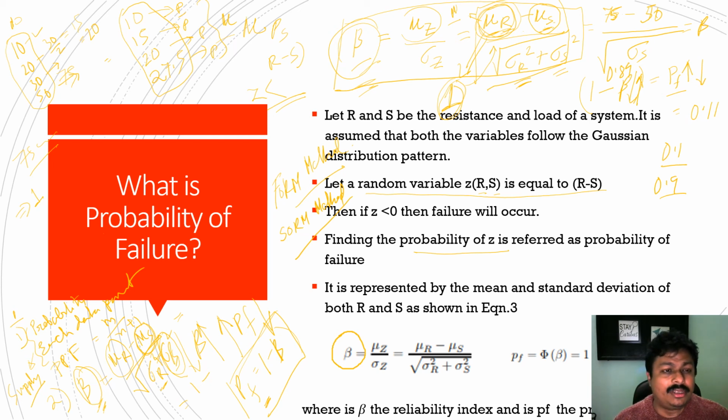And in case of SORM method, you find the moving average of the available data point for the supply data, and then you find the probability of each of the points of that moving average with the help of plotting position. Then you find the mean of those probabilities and put it into that equation. If resistance data is single, that means mean of R will be 1 then. If the resistance data is more than 1, then you have to use the same method to find mean of R that you have adopted to find mean of S in case of FORM or in case of SORM, right?